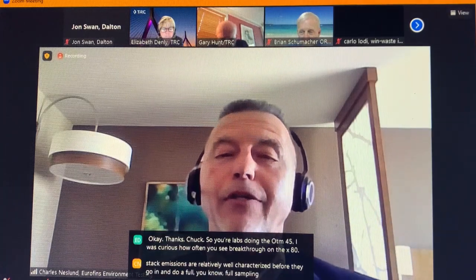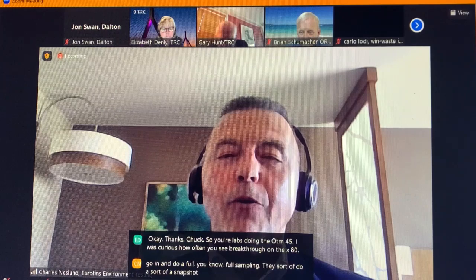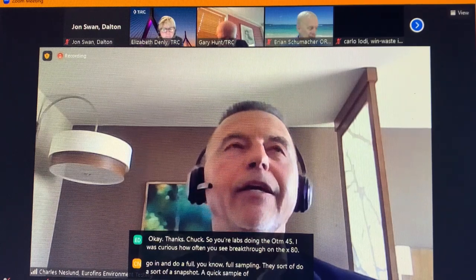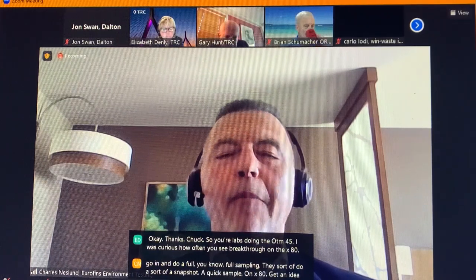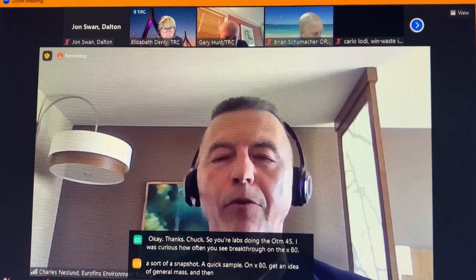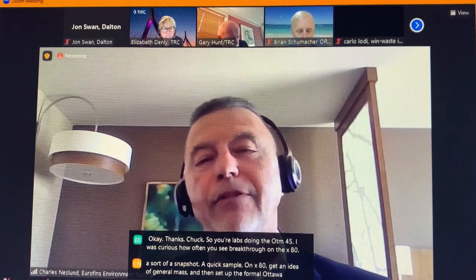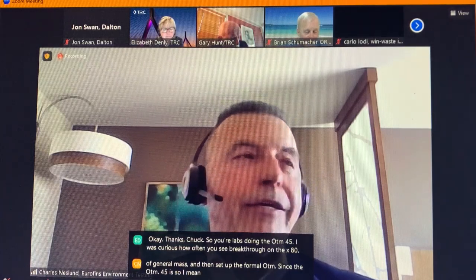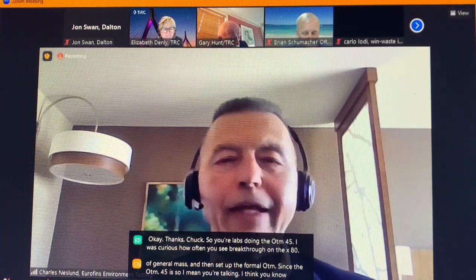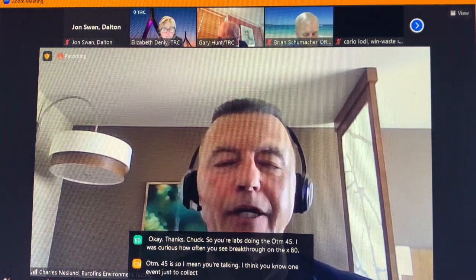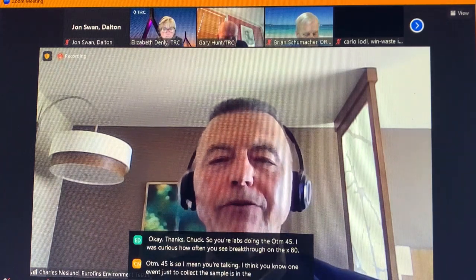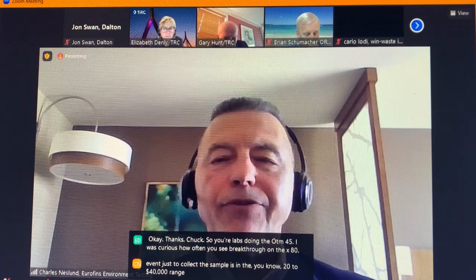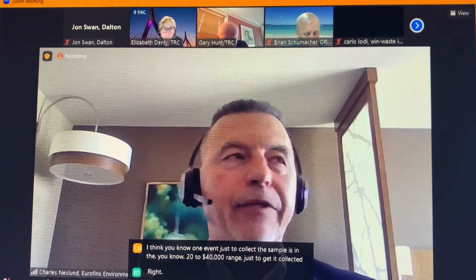They do a snapshot, a quick sample on XAD, get an idea of general mass, and then set up the formal OTM. Since the OTM-45 is so, I mean, one event just to collect the sample is in the $20,000 to $40,000 range, and that's not even doing the analytical work on it. So it's a big investment.